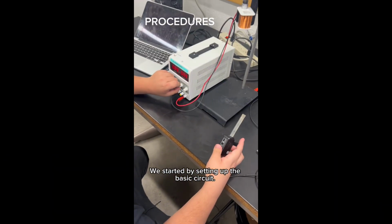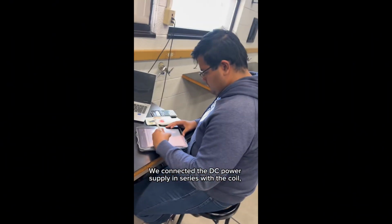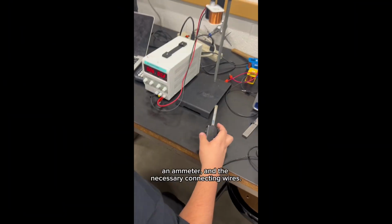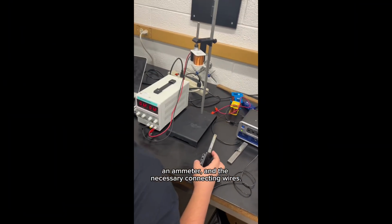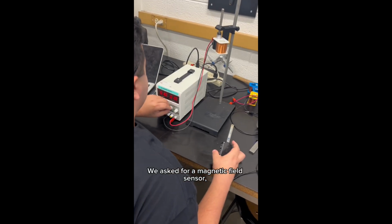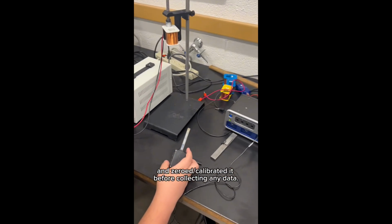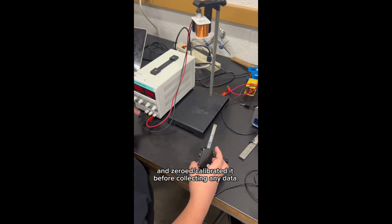We started by setting up the basic circuit. We connected the DC power supply in series with the coil, an ammeter, and the necessary connecting wires. We connected a magnetic field sensor to the interface and calibrated it before collecting any data.